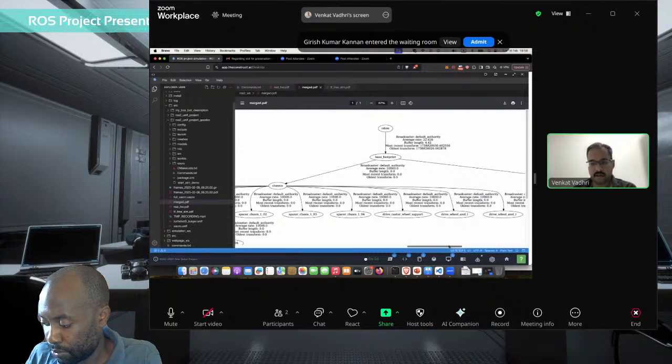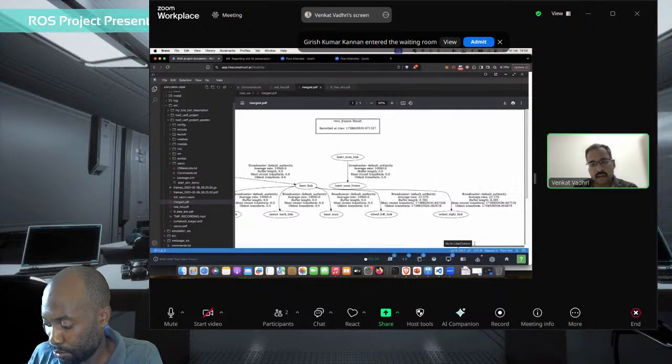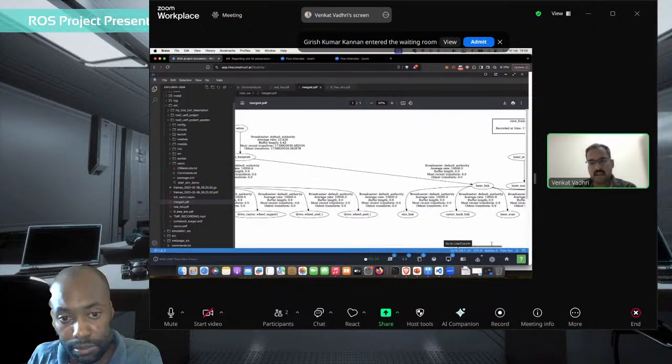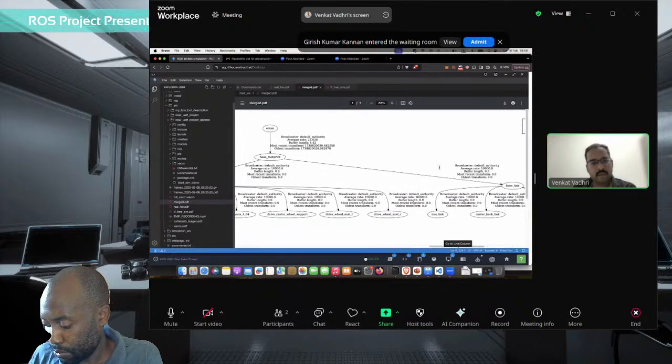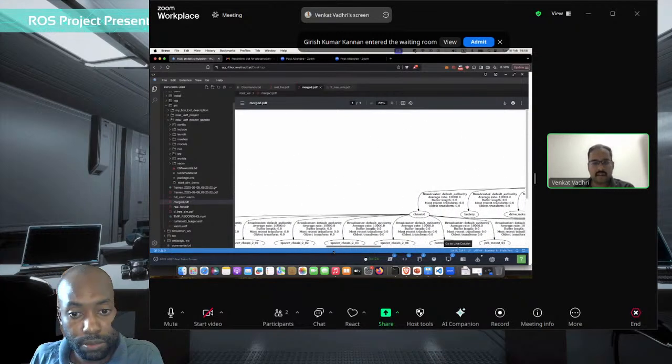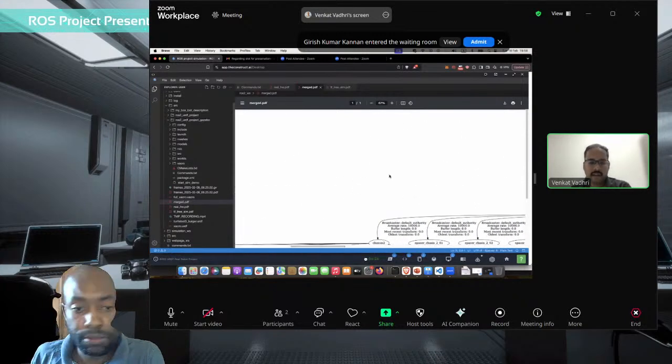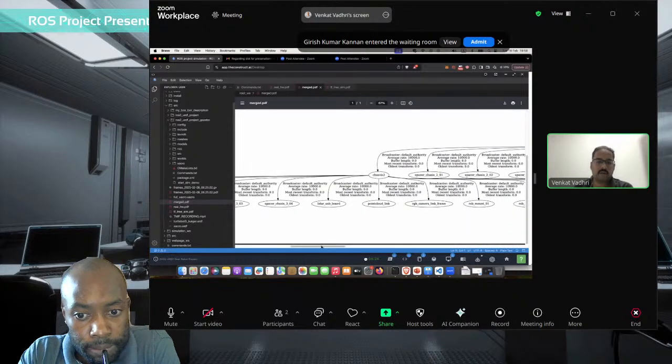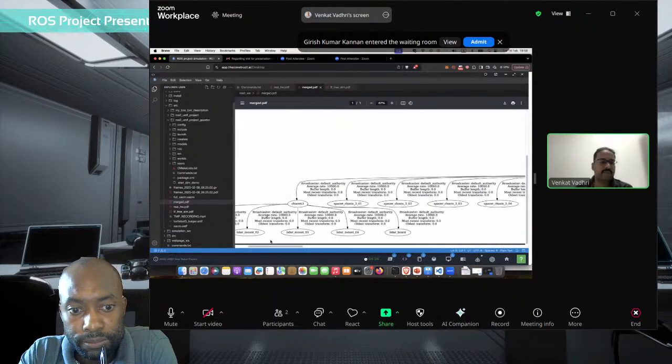When I run it on the real robot, I conditionally remove the drive wheels, and since the structure got merged, the base footprint got connected directly to the base link of the robot. The rest of the physical structure that is left intact has no impact on the real robot case that will actually run.